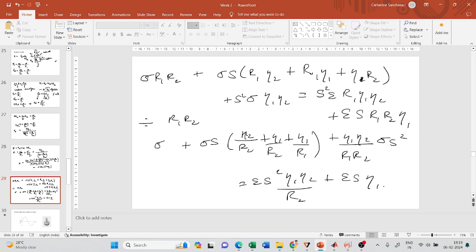You had a differential equation, so working with it was difficult, so you took Laplace transform and wrote sigma dot as s into sigma and epsilon dot as s into epsilon. And when you did that, all you did was basic algebra. So you just took LCM, multiplied it, divided it, rearranged the terms, and you got this equation.